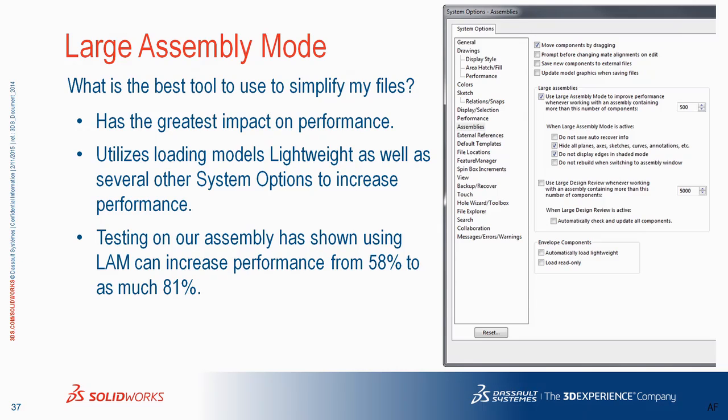It affects open, save, believe it or not, close. After you've saved and you just hit go away SolidWorks, in a large assembly, sometimes it doesn't actually go away for a couple of minutes. But it affects that. It affects graphics performance, how fast the models can move, how many frames per second you can get. It affects that dramatically. It affects rebuild times astronomically. Most of our benefit came from rebuild time.